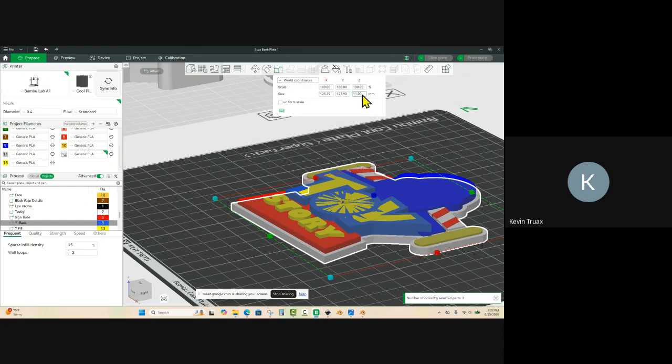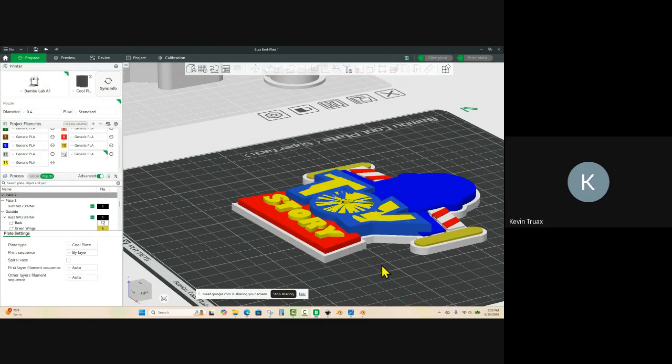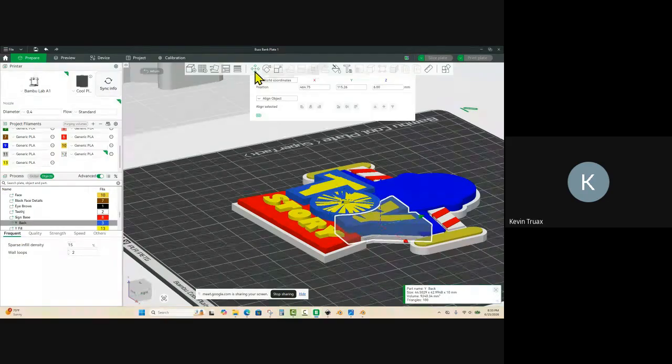So that's currently at 11. The top of that blue plate is at 11, and it doesn't need to be that thick. So I want to take this blue piece and put it on the white. Number 1. That's the first step I want to do. So let's go ahead and alt-click it, and let's move it in the Z here.